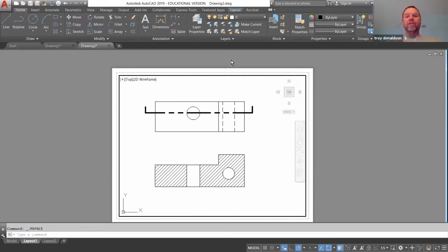And a polyline you can make any width you want. And what I'm going to do is make a polyline with the starting width kind of wide and an ending width 0. So it's going to go to a point, wide to nothing. And a little trial and error here because of the scaling within the model to paper space.